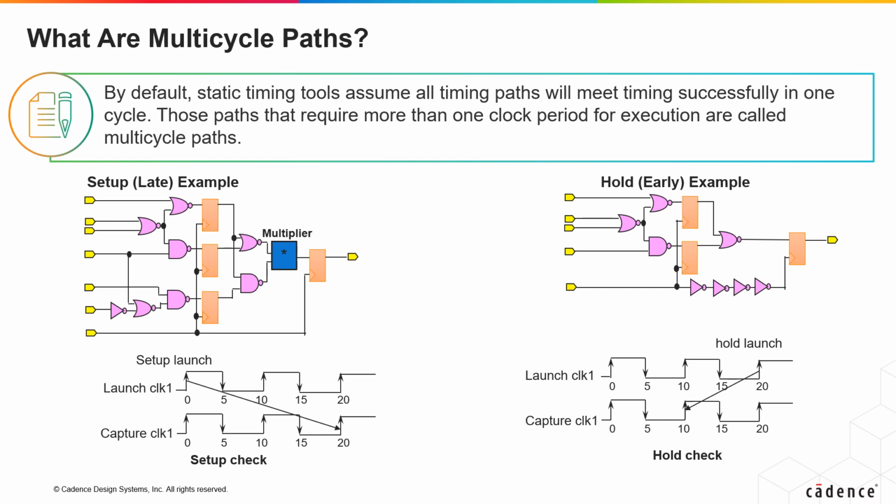For such multi-cycle paths, you don't want the synthesis tool to waste any resources trying to figure out the best way to optimize this path to fit into one cycle. Therefore, you make an exception. You tell the tool that this is a known long path and that it is a multi-cycle path so that it can skip optimizing it for one clock cycle.